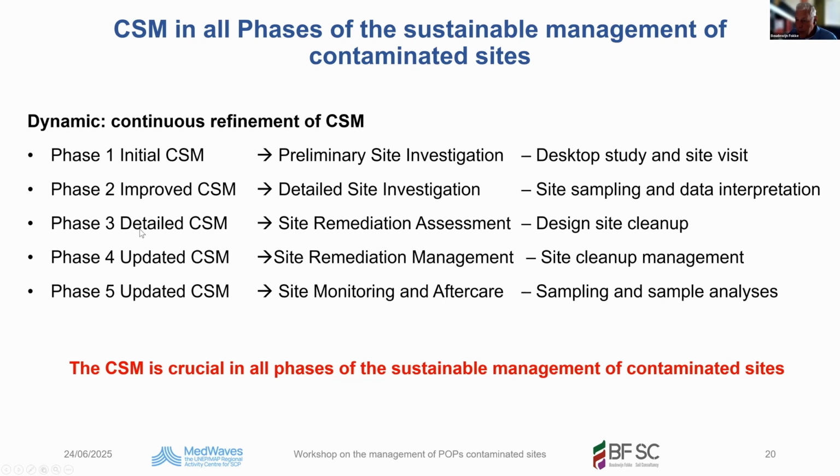Then the third phase, the detailed conceptual site model, is used to design your site cleanup. Because also in this phase, you may need to go back to the site to collect information to be able to design a cleanup. So with new information of the site, you update or detail your conceptual site model. Then we enter into phase 4, site remediation. You have carried out your cleanup, so the situation changed on site. You take away your contaminant. You have excavated so many tons of contaminated soil, so this should be changed in your conceptual site model.